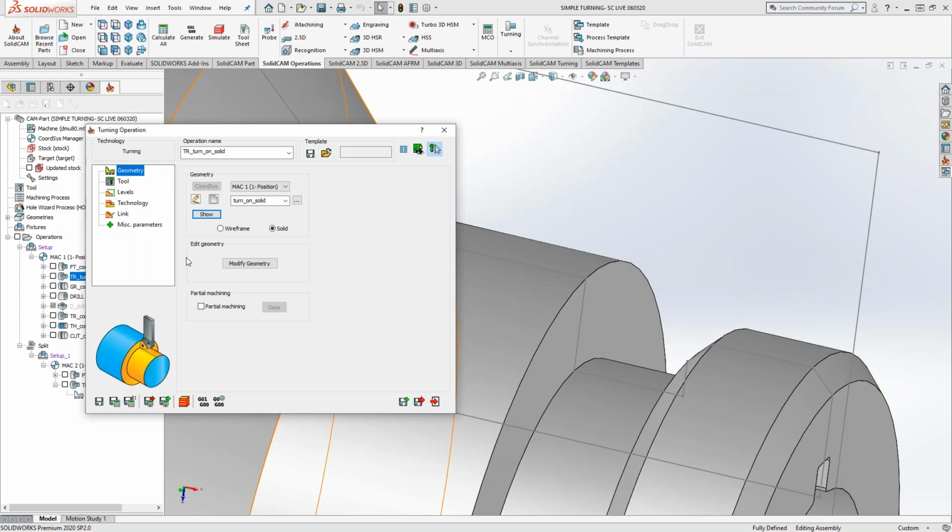So the reason I bring that up is because oftentimes in milling and turning, but here more specifically with turning, if you wanted to change something about the profile, you would want to change the solid and then just resynchronize, recalculate, reparse the model, all of that. So that's what you could do to get your internal and external corners. You can go to the original design model, or you can even do it here in your feature manager and change those corners to fillets or chamfers.